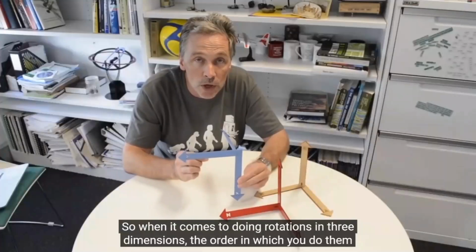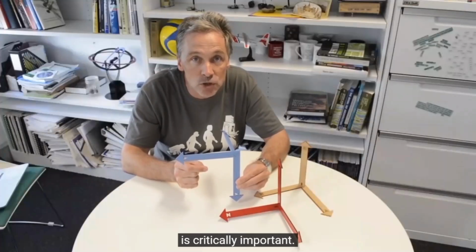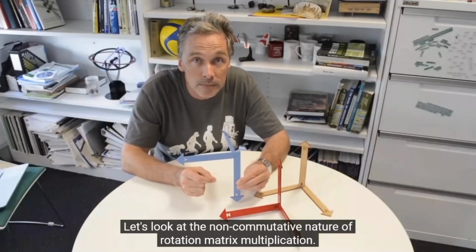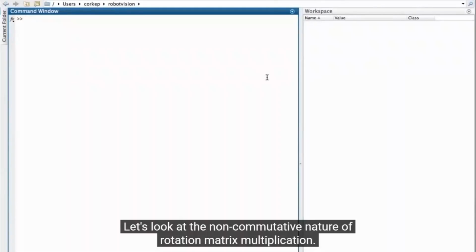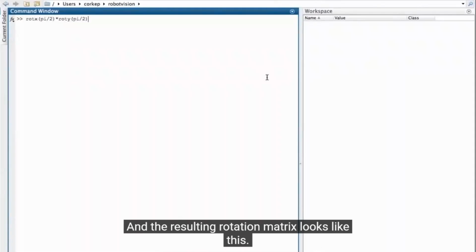So when it comes to doing rotations in 3 dimensions, the order in which you do them is critically important. Rotations are not commutative. Let's look at the non-commutative nature of rotation matrix multiplication. I'm going to have a rotation of 90 degrees about the x-axis, and then I'm going to rotate by 90 degrees around the y-axis, and the resulting rotation matrix looks like this.